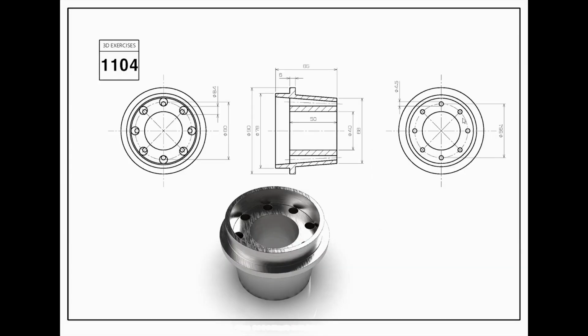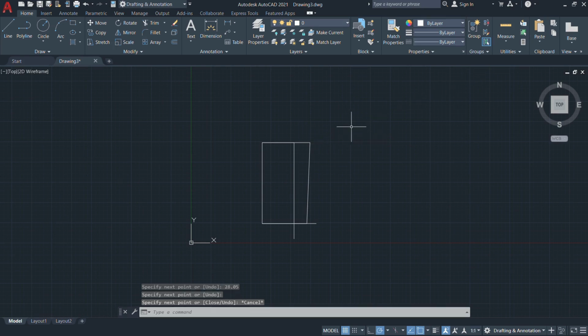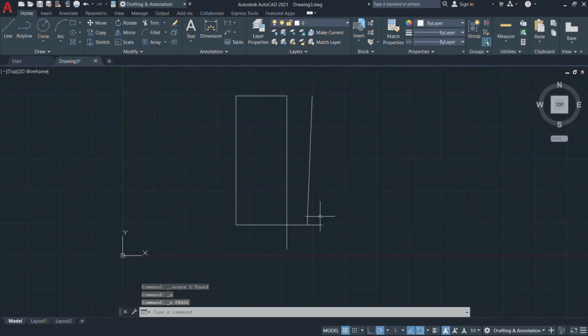Again, the bottom portion. In the bottom view, it is clearly explained as 56.1. Half of the value is 28.05. Just mention it, then connect the two opposite endpoints. Now we get the center line. Next, we draw profiles from this portion itself. Either we can delete the bottom line completely or use it as a reference. That's why I use Ctrl plus Z to undo right now.